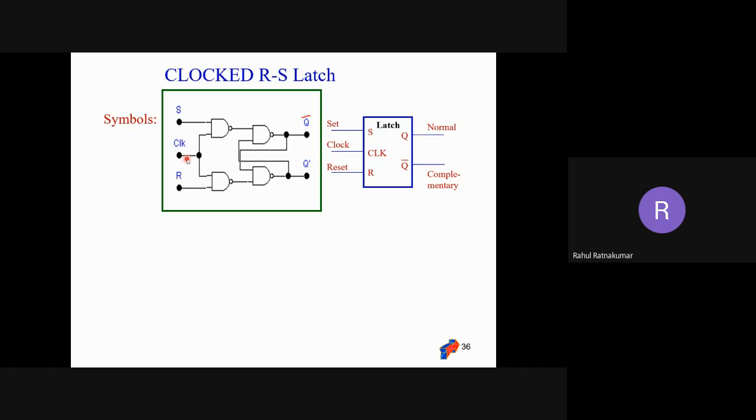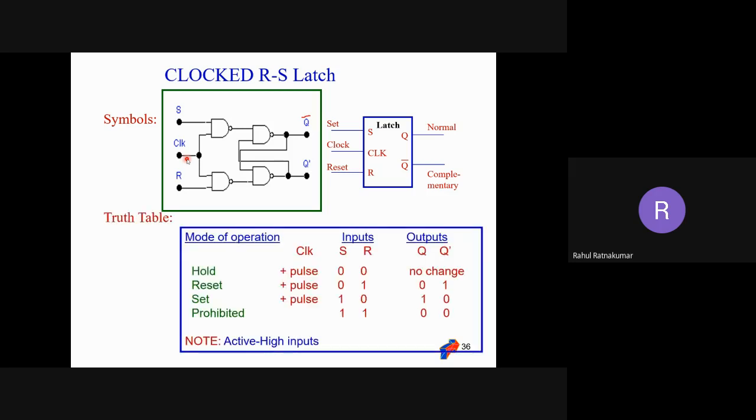Likewise, we can have a latch using NOR gates also. You can see the pulse is only a positive pulse or negative pulse. So it's level, positive level, and it will be activated based on inputs S and R. My output will be changing, right? If S and R are 0 during the positive pulse, there's no change in the output.